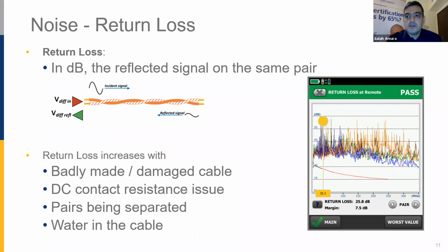Do you have anything to add, Werner? I would say PoE is not really an application. You deliver power over the cable. We certify the cable for data communication. We can do extra measurements to give you a better guarantee or warranty that the PoE will work, which is the resistance unbalance. But PoE itself is not an application that we can say, okay, if you test Cat 6a, then PoE will work. That's not an application standard.